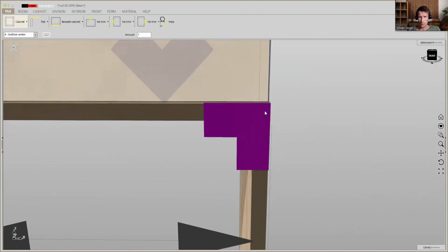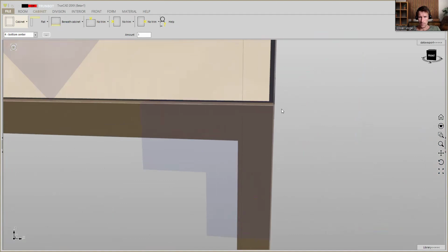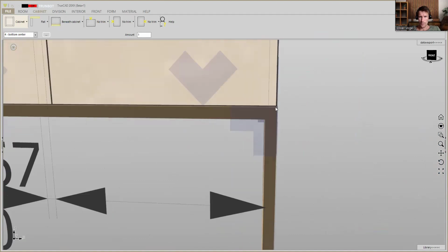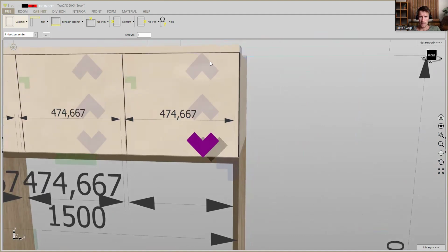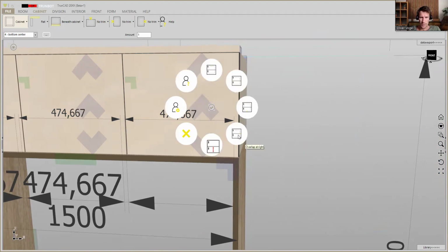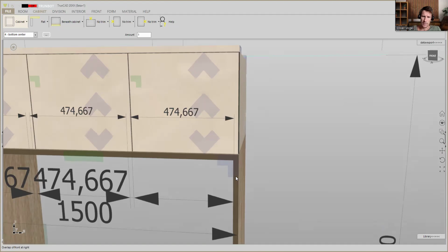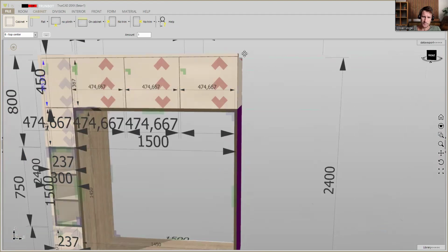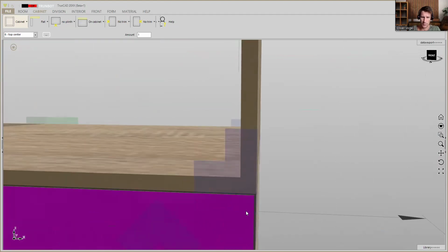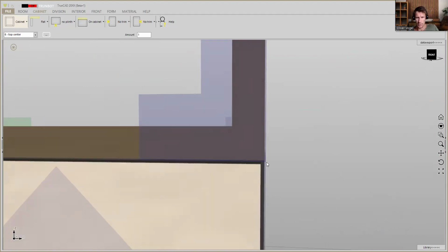And here we can prepare it also to extend the fronts on the right side. We click here on one of the three smart clicks and go on symbol overlap at right, type in 3 mm. Why is it 3? Because in my default setting, the front has a space of 3 mm. Here we can also measure it.